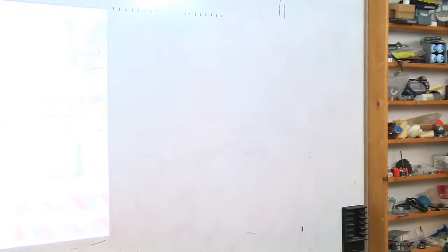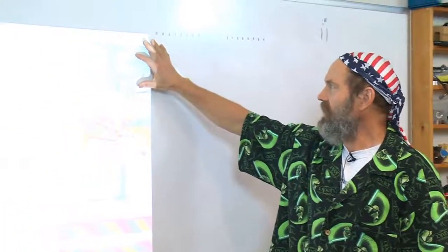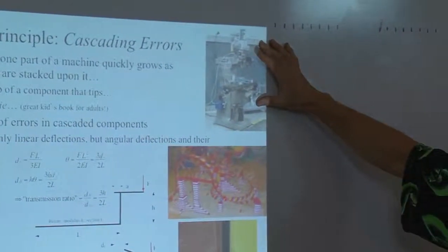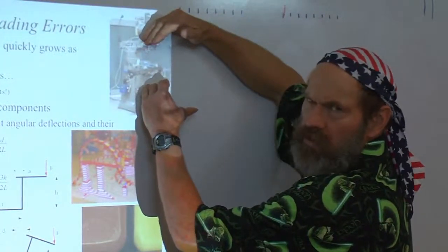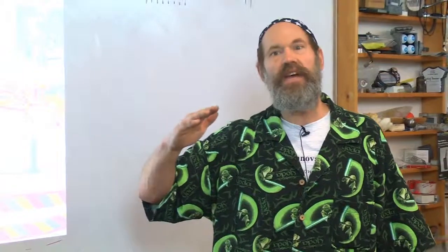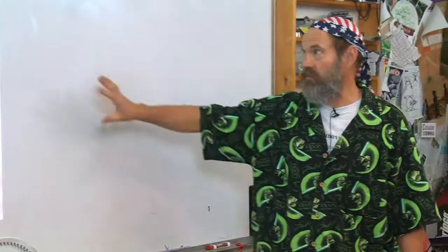Very, very important. When you think of a milling machine, for example, big, rigid cast iron, it actually has got little spaces everywhere in it. And this super precision machine with little spaces everywhere, you start machining and things move a little bit, and it opens up a little bit. You normally don't care. But if you were designing a machine to make the optics that go into the wafer steppers that go to make the silicon wafers, which go into making everything electronic, that cascading of errors can build up. Very, very critical design rules.